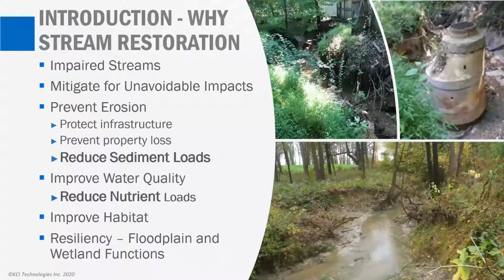This could be a week-long topic. I'm going to do a 30-second slide on it. The way we use our land can cause stream instabilities. Agricultural practices such as clearing forest and channelization can lead to channel instability. Also, development alters hydrology by introducing storm drain networks and impervious surfaces. Impervious surfaces include areas that impede water from infiltrating into the ground. So rooftops, roads, sidewalks, etc. So these destabilize channels, which can lead to excessive erosion. And channel erosion contributes a significant amount of excess sediment and nutrients.